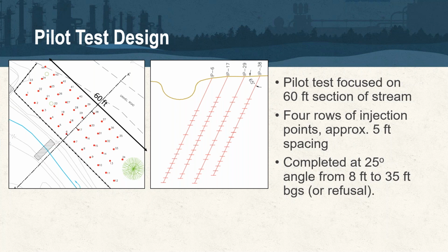Now, if you're going out with those technologies on the front end, you can certainly optimize that RDC process that I had covered today. And so, we know that, okay, the plume is this size. We've defined that. Now we're going to go out and get our soil and groundwater data to be able to use in combination with the high-res information, especially that HPT. HPT is a critical tool, I think, whenever you're doing PRB designs, because it really helps you ID where those transmissive zones are, and you can sample those, and it gives you really good mass flux measurements or calculations.